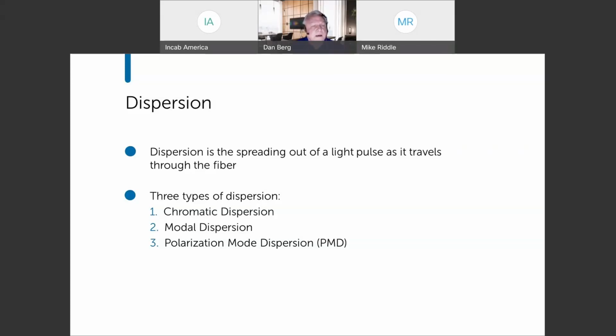What we did to correct that is we came up with a graded index multimode fiber. What this does is it basically speeds up the light as it tries to escape out the cladding of the fiber. So this wave moves down the length of the fiber in a sinusoidal pattern. In other words, it's going faster, it goes up, and when it hits the cladding, it's bent down towards the core, and it goes through this sinusoidal wave all the way down the fiber.